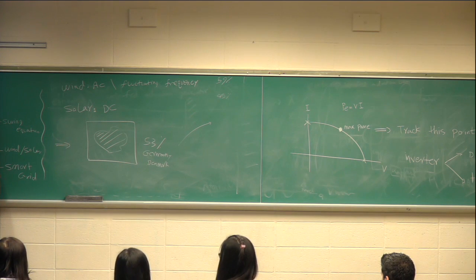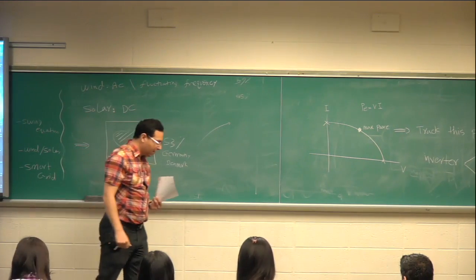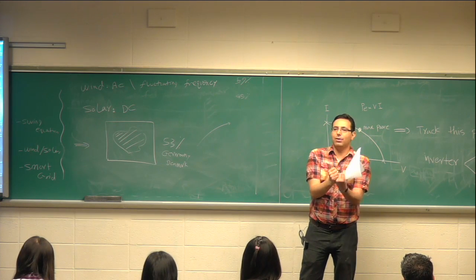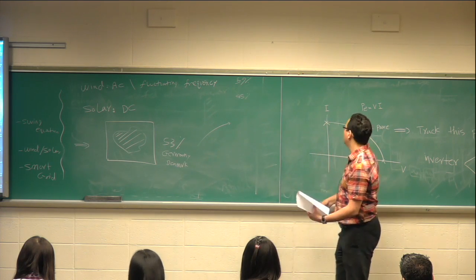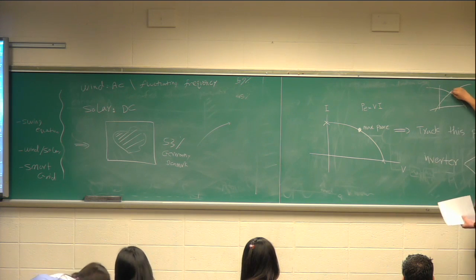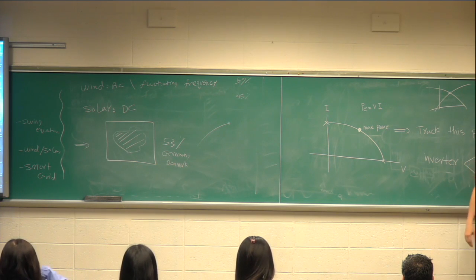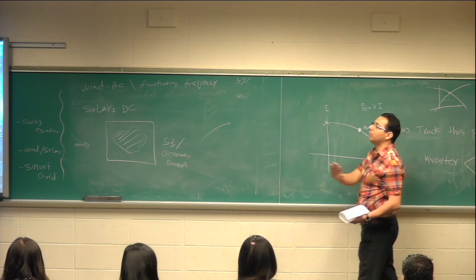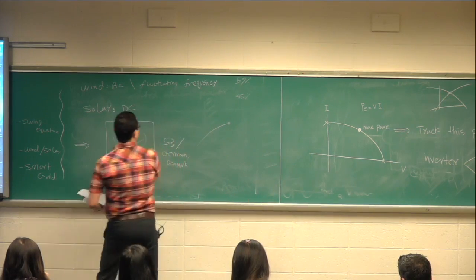Some challenges are about the business. Like we talk about unit commitment, we talk about the electricity market. And that's the private sector. 24 hours before operation, you're a generator, you bid in the market. You would say, tomorrow I'm going to generate 2 megawatts of power. You remember we talked about the supply curve, the demand curve, and then we got the intersection. 24 hours before operation, you have to come up with a supply and demand curve. And if your business is based on wind, 24 hours before operation, your forecast could be 80% wrong. And then this could be a huge loss. So in terms of the business, there's a challenge.